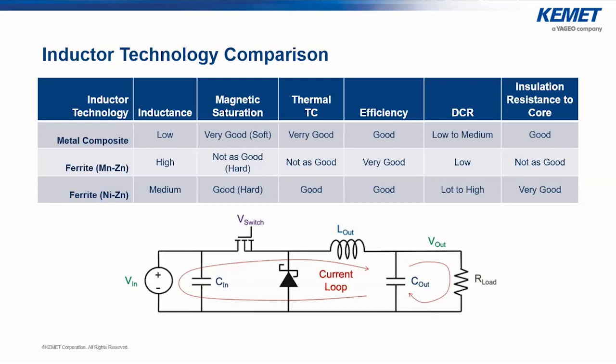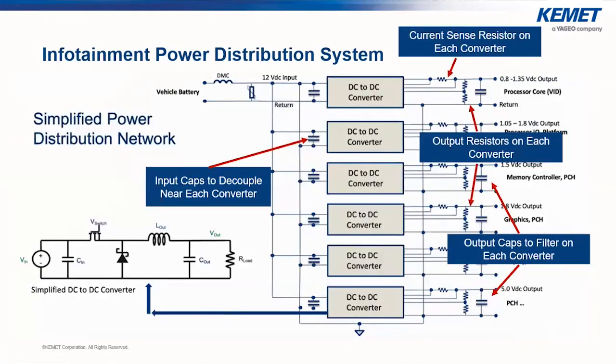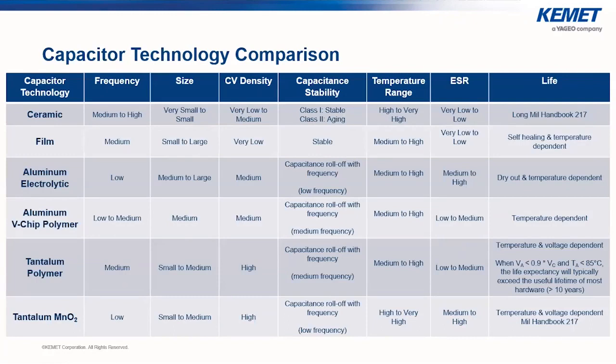Is there anything to be considered regarding lifetime limitation of polymer capacitors? I guess it's polymer tantalum capacitors. Polymer tantalum, yeah, of course. If we talk about the tantalum capacitor, as I said, we need to worry about derating, which in the tantalum polymer is not the case. In the MnO2s, the derating is crucial for the life of the capacitor.